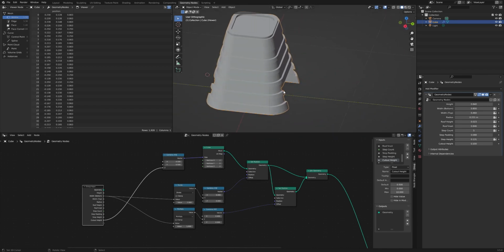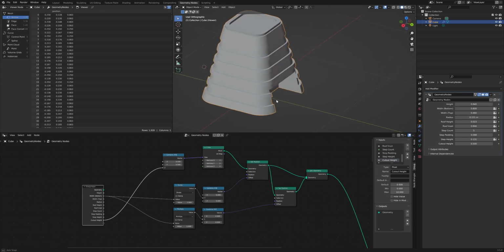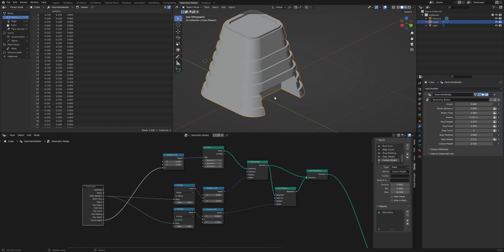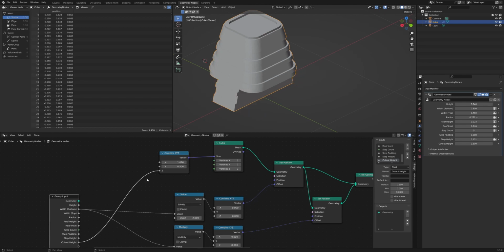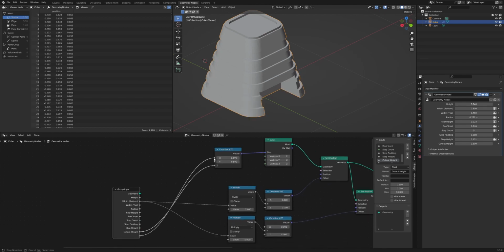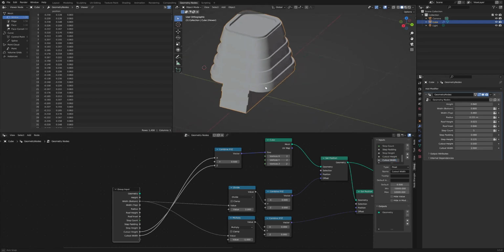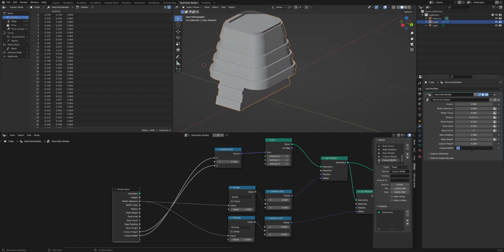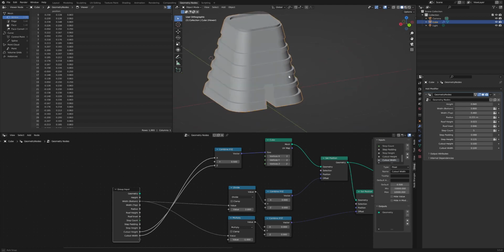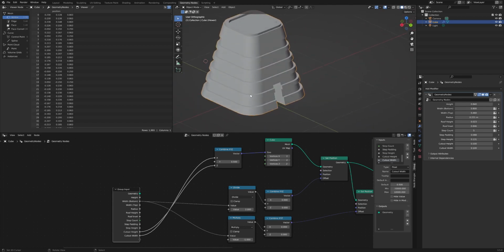The next thing I also want to be able to control is the offset of that position. So at the moment, it's automatically centering itself to be level with the width. It would be nice if we could control how far in or out that is also happening as well. And also the width. So actually, let's do width first, which I think is that factor there. Yes, it is. So if we do cutout width is going to go into X. And let's just call that R1, for example. Or even actually a 0.1. Might be quite a nice little kind of doorway type cutout, which works quite nicely.